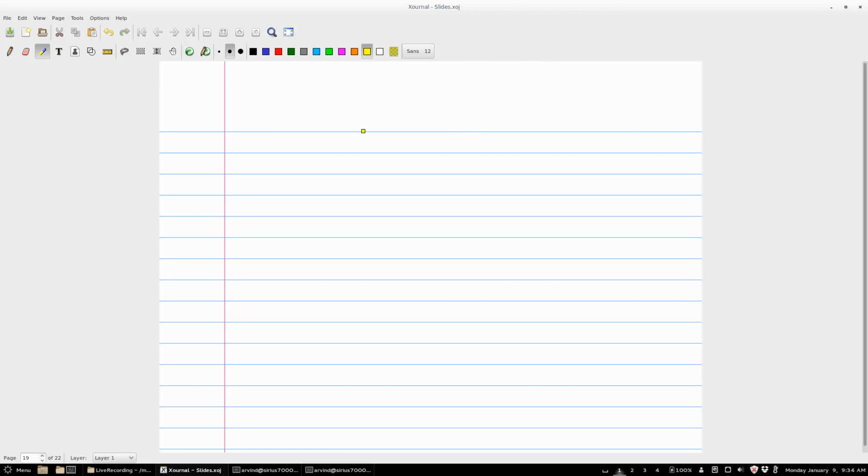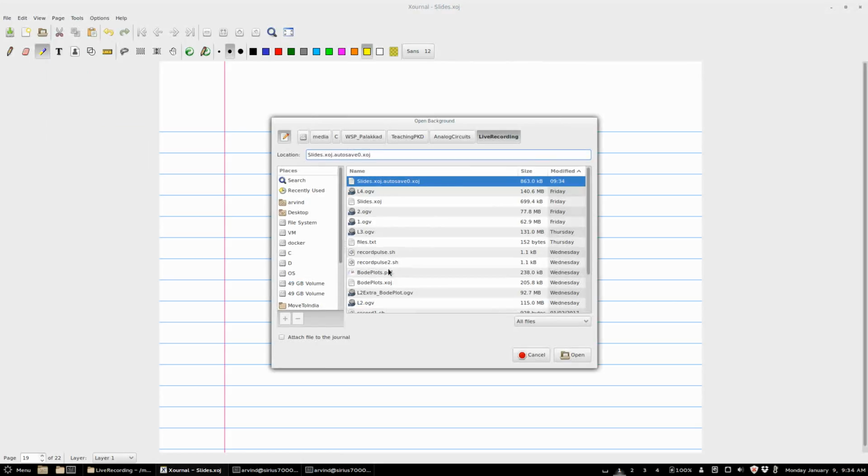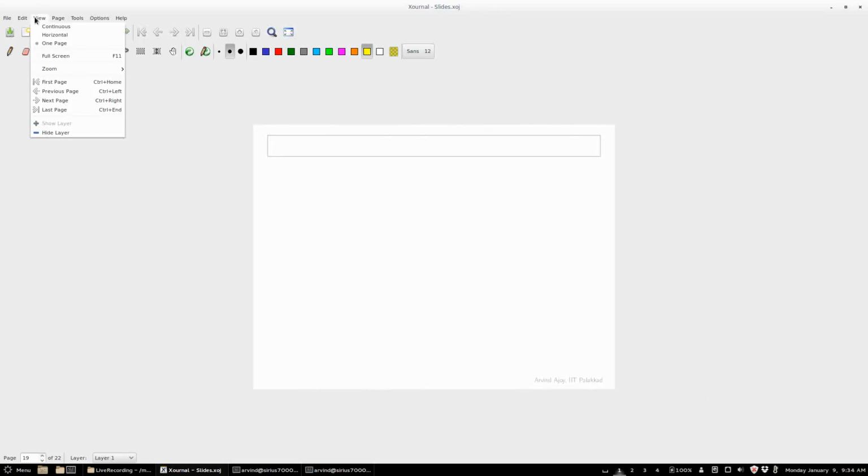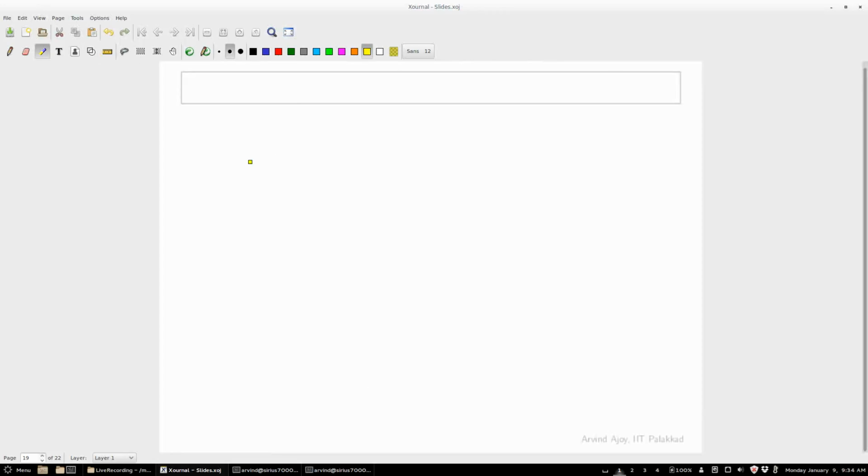And then this is the DC component. So you subtracted the RMS value of the DC component from the RMS value of the total signal. So what are you left with? Basically the RMS value of the AC signal. As an exercise, I want you to go and think about this. It will become clearer.